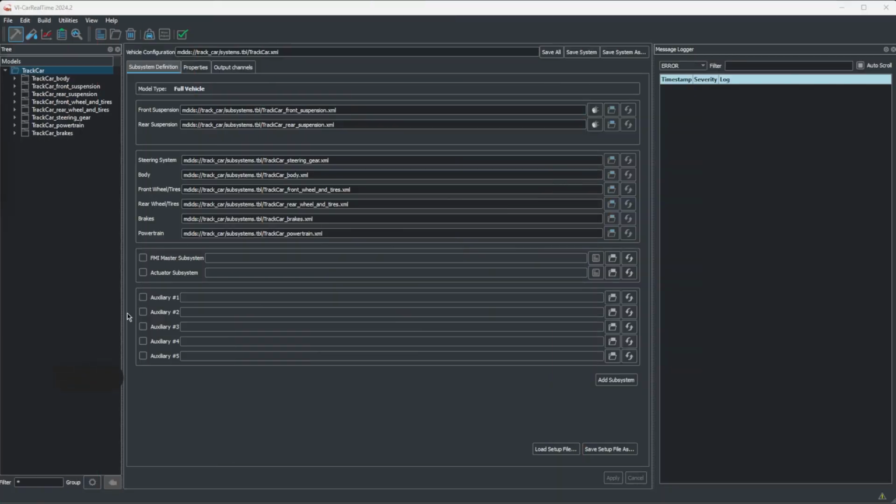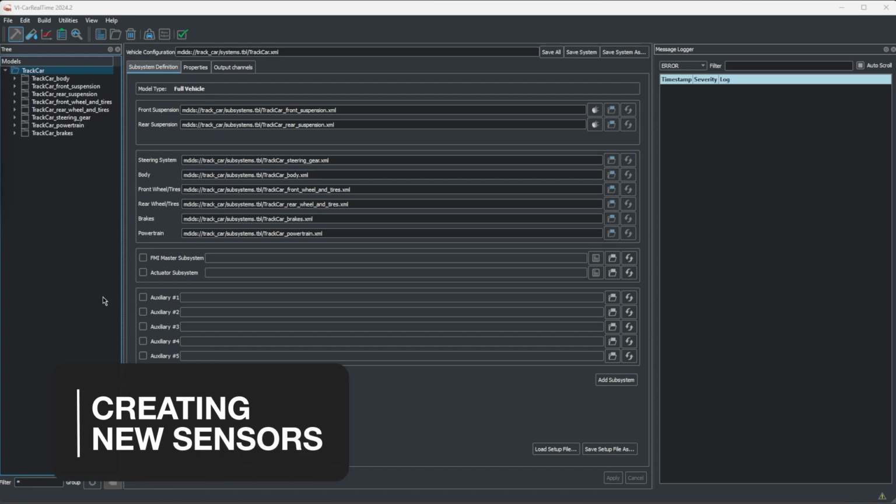Now, let's focus on installing the sensors that we need on the car in order to be observing and quantifying these characteristics. We have to install an accelerometer to the seat rail. This gives us a consistent reading of acceleration based on the chassis and suspension properties, ignoring the influence of the seat itself on comfort for now.